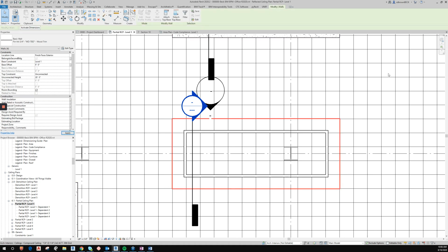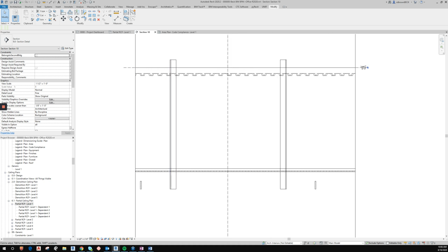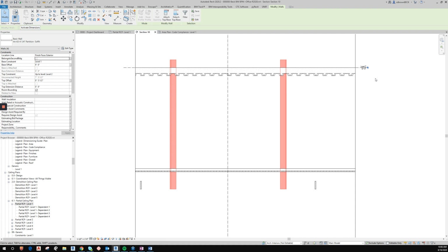I'll set that to 9 foot, and then this trim is, say, 6 inches tall, so 5.5 inches tall, and then our support wall is going to be again at 9 foot, and it may go up as we define this, and that goes up to level 2, and then minus 5.5 or whatever your floor height thickness above. So now you can see that you have the, I did it above. Let's select previous. That should be a minus.